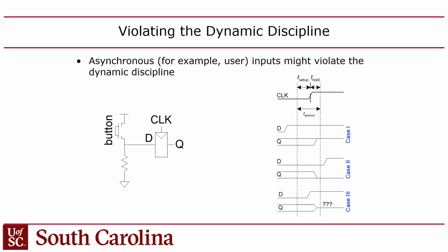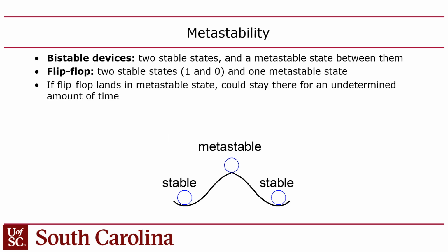Not likely with the switch, but think about a network packet coming across the network. There are a lot of bits coming in from the network and it happens continuously, 24/7. And those are all inputs. The reason they're inputs is because they're coming in on a different clock, right? Your computer, when it's on the network, is sampling inputs that are being driven by a clock on another computer that's not synchronized to your clock, right? And so there's no guarantee ever that input bits will not arrive during the aperture period of your sampling flip-flop, right? So that's just something you have to deal with.